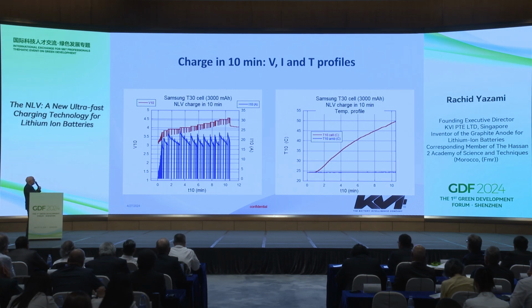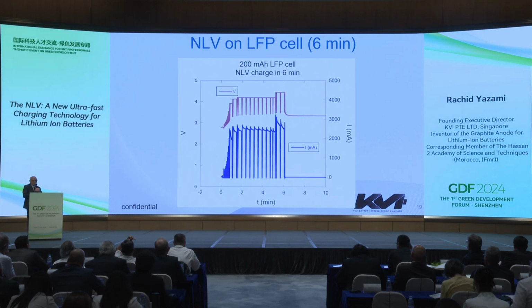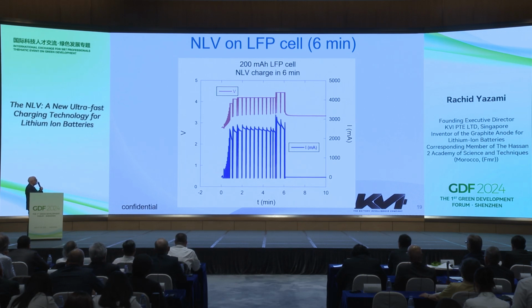We have also broken a world record, for an e-cigarette, electronic cigarette system. We have a collaboration with a company in Switzerland, and they asked us to see whether the batteries can be charged in below 10 minutes, and we did it in 6 minutes. So this is the world record of any charging time for a lithium-ion battery. This battery is using LFP, which is lithium iron phosphate cathode, which is very fast. And we were able to charge it fully from 0 to 100% in 6 minutes without exceeding 50 degrees C.